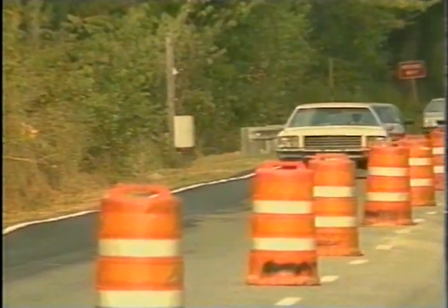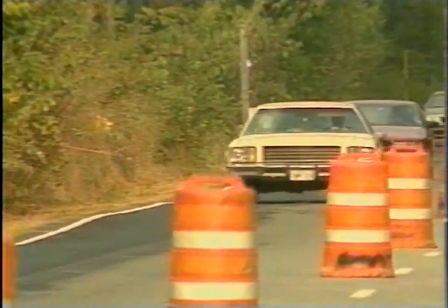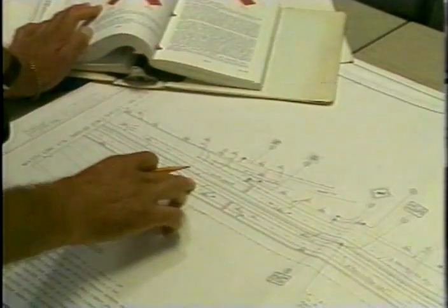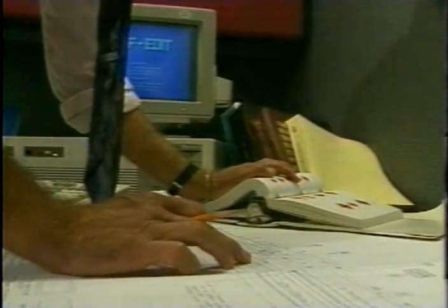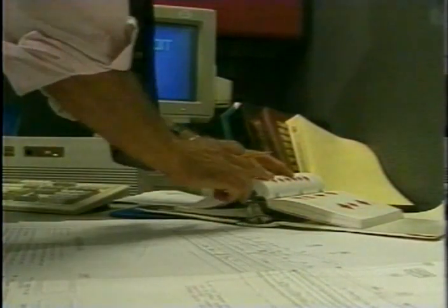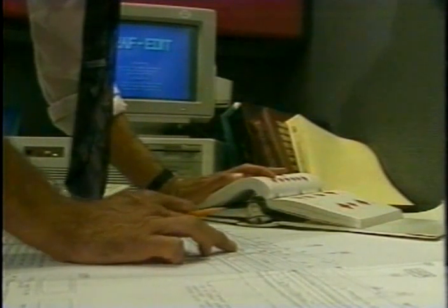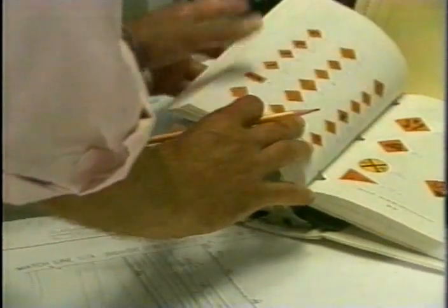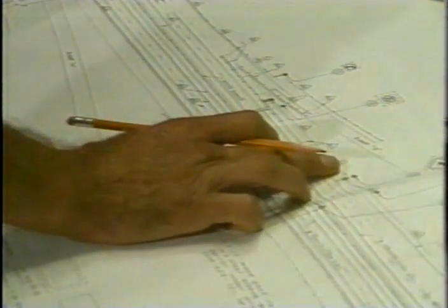Balancing safety with public convenience is a large part of the traffic control plan. Let's look generally at the plan. A traffic control plan is a blueprint for handling traffic through the work zone. It is required for all federal aid projects. It should include traffic control strategies, staffing requirements, use of specific devices, and design of geometric features such as tapers.